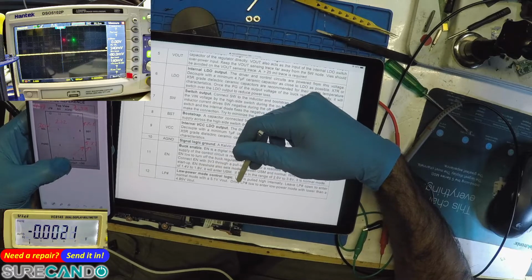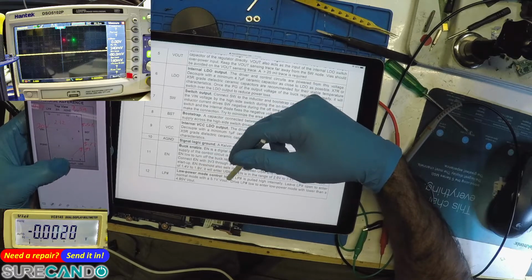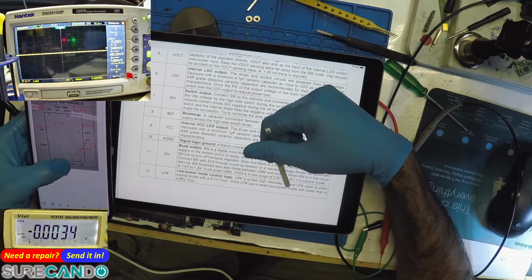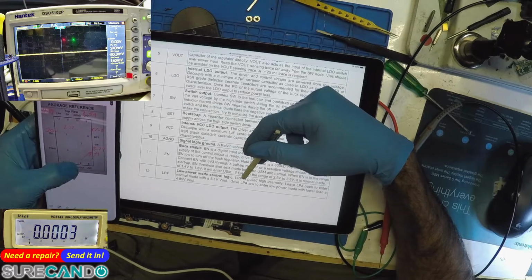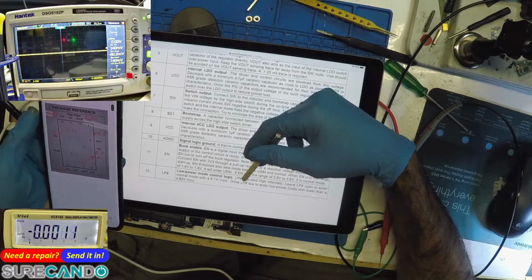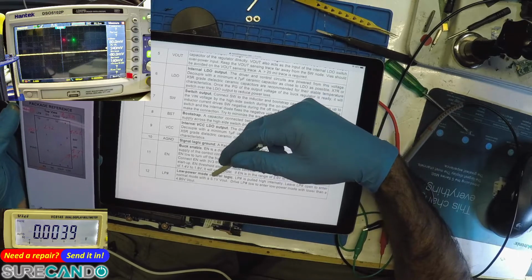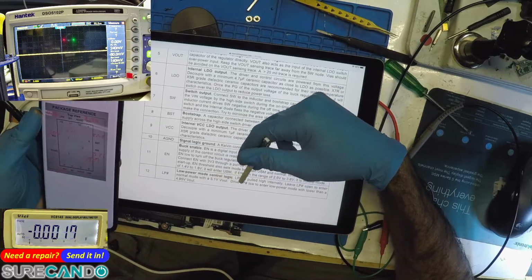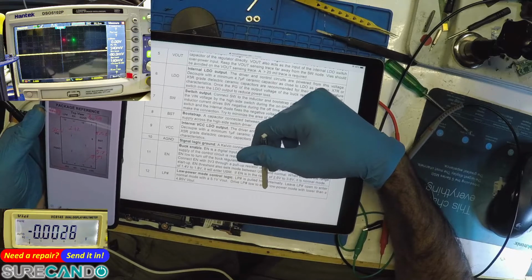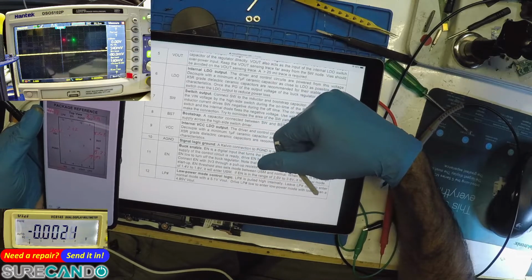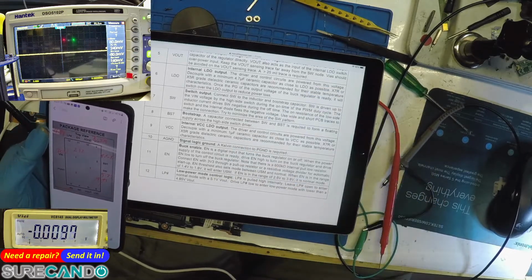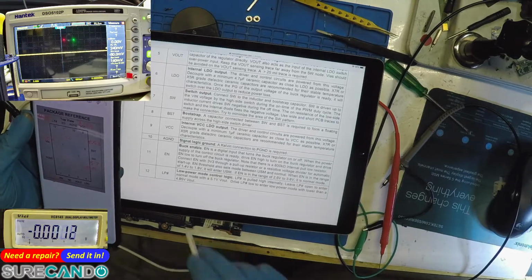Low power mode control logic. It's pulled high internally. That's why we got 4.8. Leave LP open to enter normal mode with a 5.1 voltage out. Drive LP low to enter low power mode. Oh, okay. So it's not a low power mode, okay.